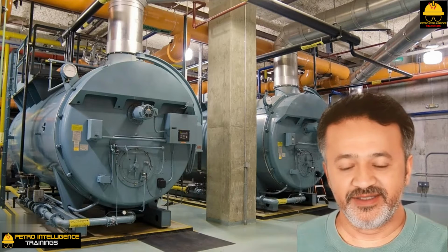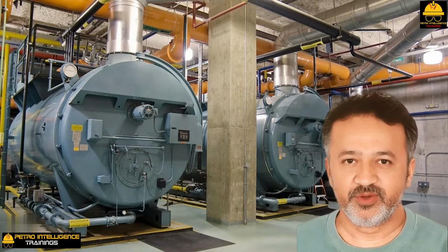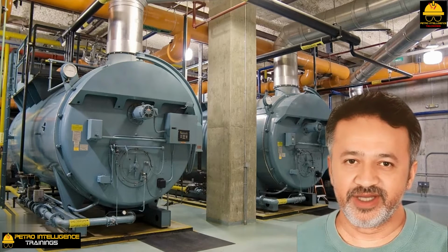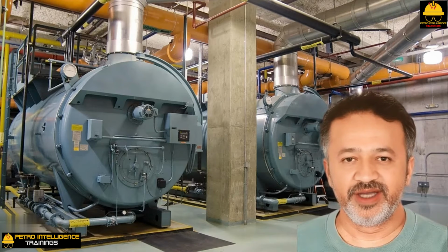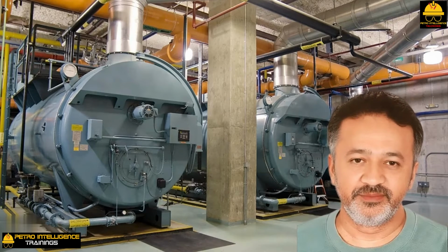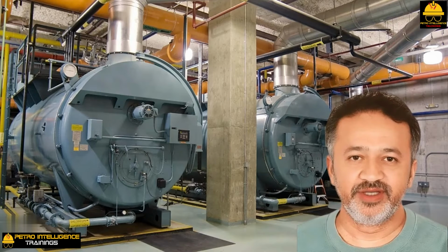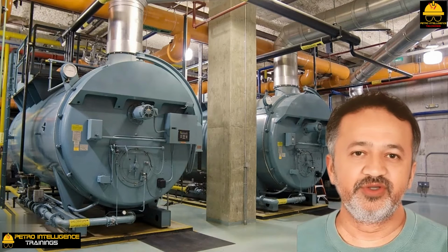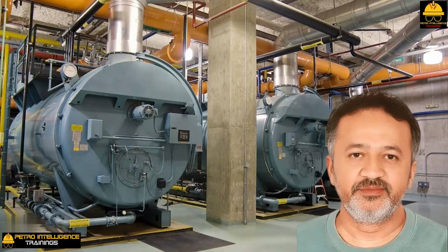Boiler blowdown rate. Although boiler feedwater (BFW) has been treated to remove minerals, residual contaminants, carbonates and silicates are still present. These minerals, especially the silicates, are bad, as to some extent they are going to be entrained into the generated steam. The biggest problems with entrained silicates or TDS, total dissolved solids, are drying out on the steam superheat coils, which then fail due to localized overheating, which results in superheat tube failure.